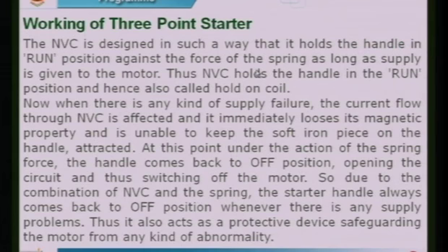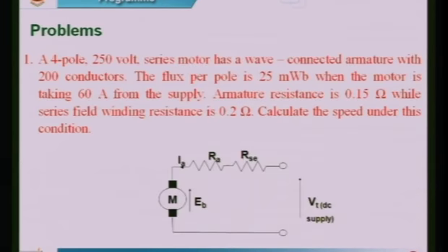So this is how the 3-point starter works. So what do you mean by this starter? Starter is a variable series resistance. It is connected in series with the armature to avoid the inrush of current, to protect the windings of the motor and also the commutators.